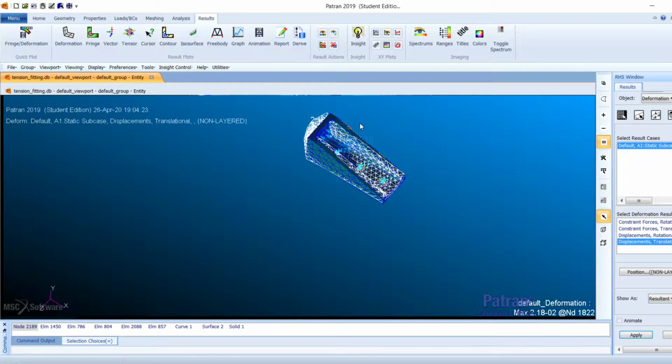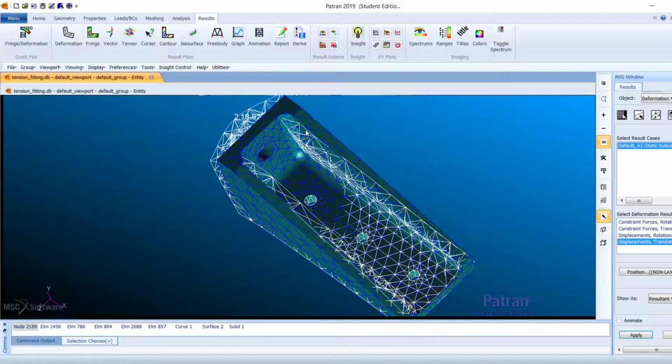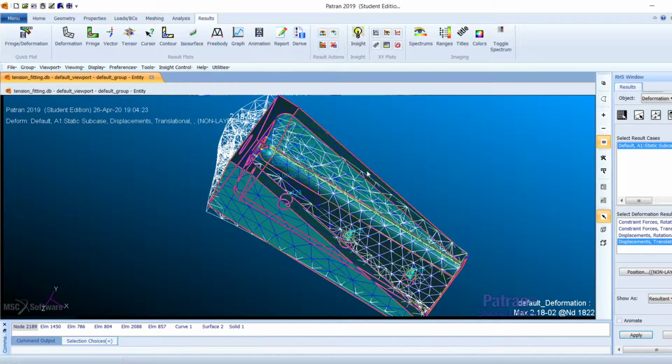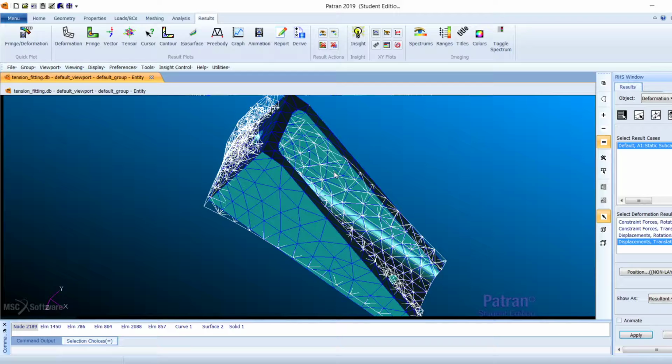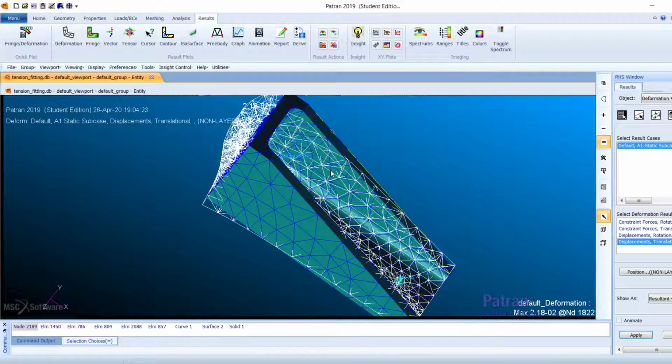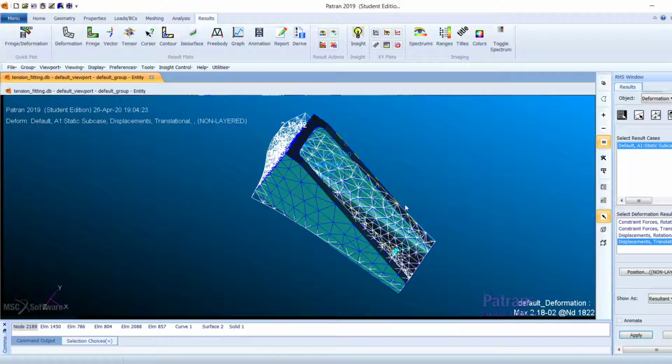This must look something like this. If you have used a bigger type in the meshing, if you use a higher value of the mesh, how it works is gonna be a little different because the system will think different things, and this result is gonna look really different. So if you use a higher mesh, it's gonna take a little bit more time. It's gonna be a heavier file, but it's gonna have better, more accurate results.